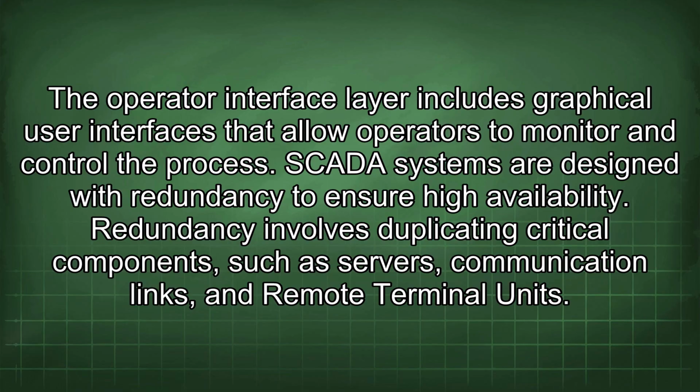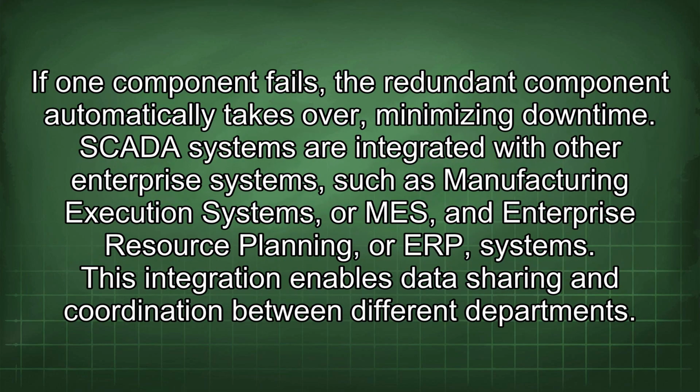SCADA systems are designed with redundancy to ensure high availability. Redundancy involves duplicating critical components, such as servers, communication links, and remote terminal units. If one component fails, the redundant component automatically takes over, minimizing downtime.